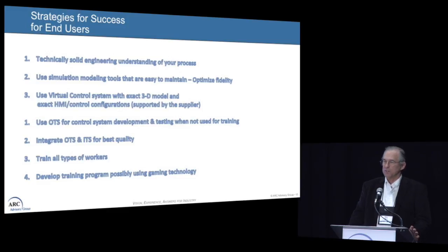Don't go overboard with simulation. You can simulate to death, and you could spend untold amounts of money to get more and more fidelity. A lot of times, part of the training simulator is to train on the control system. You don't need high fidelity to train on the control system. You need to navigate and press and see how the controls work. And you need to test off-mode situations, off normal.